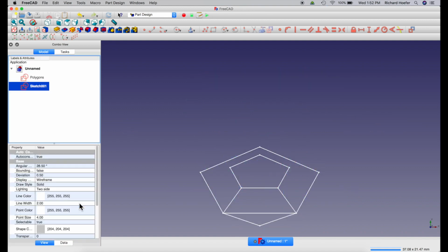Next, we will copy and paste this sketch and turn the visibility of one of them off. If you decide later on to change your z or theta value, there is a simple way to update the original face to the new values instead of resketching the entire thing. I'll touch on that in a moment, but first let's finish this panel off. I like to label the sketch with the visibility on with the z and theta values I used to make the face, so I know which sketch is which.